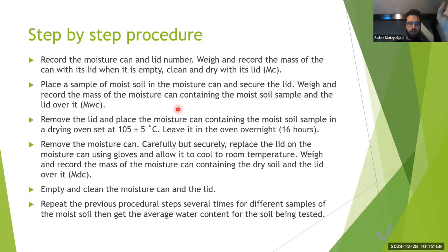As we spoke before, the temperature of the oven is going to be between 105 and 110, or you can have 100. It's fine. Usually you need to do more than 100, because 100 is the boiling temperature of the water. If you want water to evaporate, you need to get there, right? This is where the European and American standards can be different. I would usually just leave it overnight, and you're going to be happy after it.